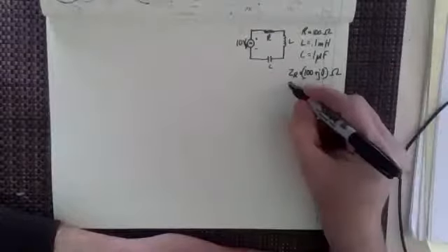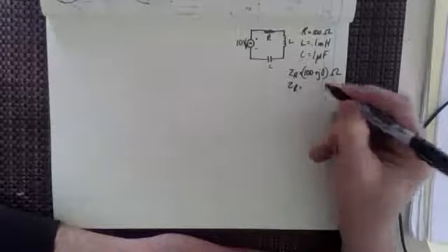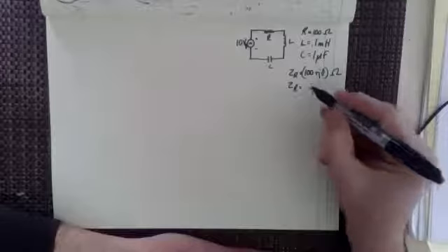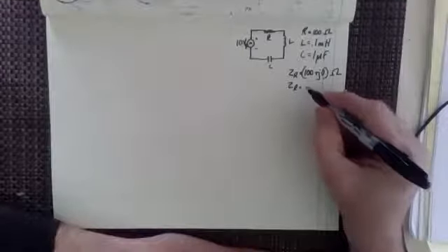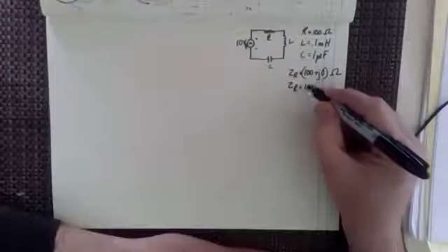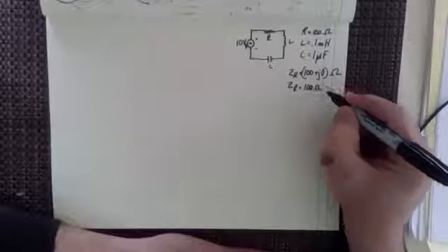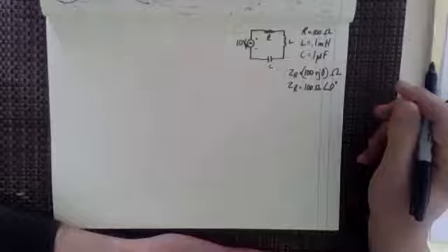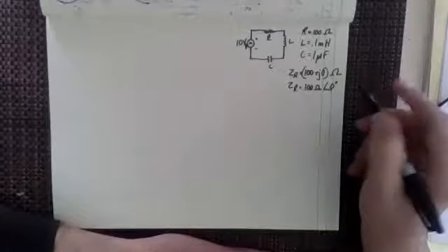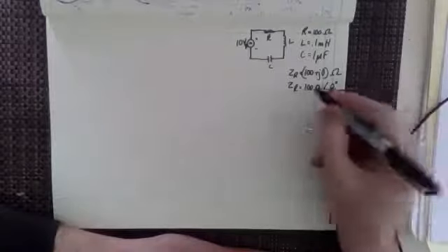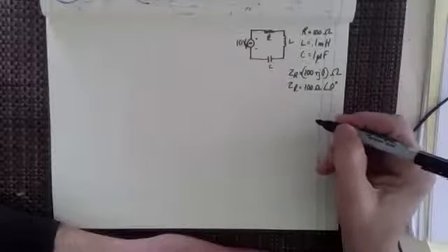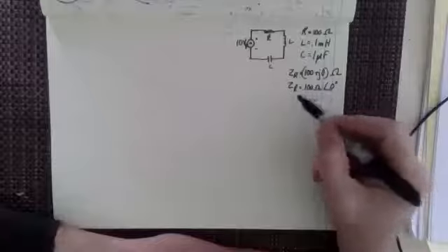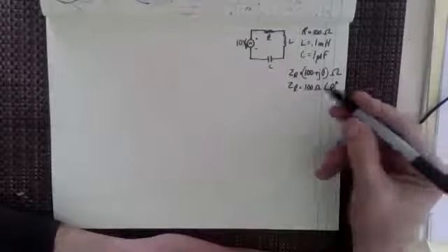And if I wanted to write that in phasor form, because we may be multiplying and dividing over the course of this lecture, I would say that would be 100 ohms at an angle of 0 degrees. I don't think anybody should be surprised about me writing this in the A plus jB rectilinear complex number notation, or in phasor notation.